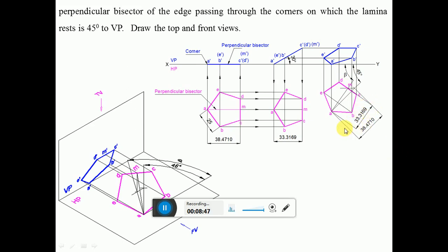Then once you get that, we have the point M and we have a line now. Through M you draw a perpendicular to AM. From M, by using the protractor, you measure 90 degrees to this inclined line and draw a perpendicular line. Through M, you measure the length of M to D and M to C, both are going to be equal. With M as center, cut an arc on this line and on this line by using the compass. Then measure the length from M to this point. From M, you cut an arc on this, so you get this point.